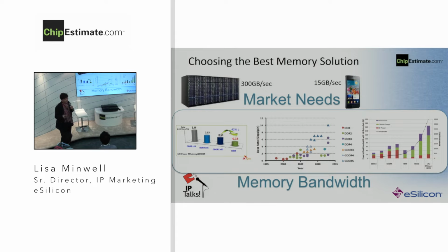Now, our ASICs, many of them are greater than 1,500 pins. So you get into a pin limitation issue as well when you're trying to manage all of these data buses to this external memory. Now, from a power perspective, the power needs from a system level remain constant. So what happens is, as you add all of this external memory and you're having to route to all of this external memory, your system power becomes an issue and being able to manage the system level power.